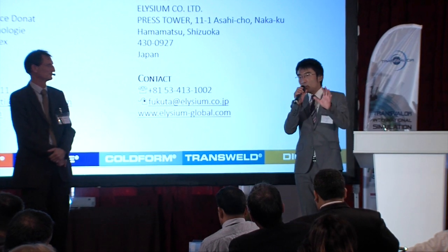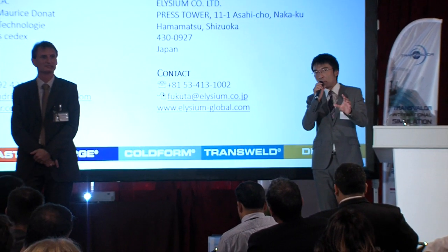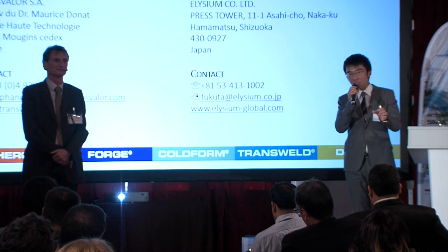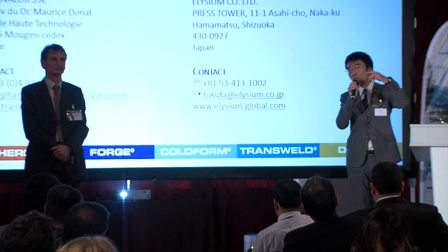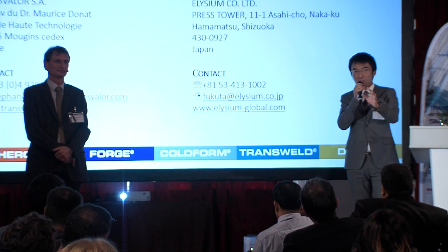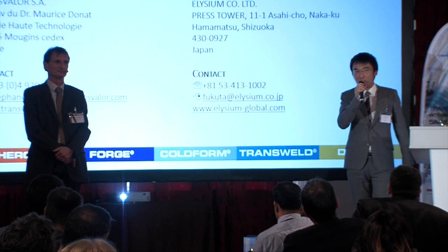Yeah, you can set up the threshold for the fillets. For example, if you would like to defeature the features within 1 millimeter, then you can set up that 1 millimeter. Or if you would like to remove the features between 1 millimeter and 5 millimeters, for example, you can set those kinds of parameters as well.